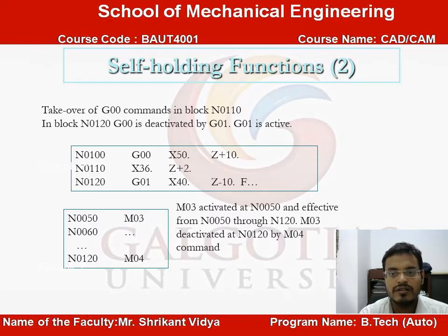Similarly, G01 is linear interpolation. So if you write a G02, then G01 will be deactivated. This is how the holding functions work. Suppose in block number N0110 you are writing G00, so movement in air is taking place. Now in the next block N0120 you are writing G01, so G00 will be deactivated, and now G01 will be active.